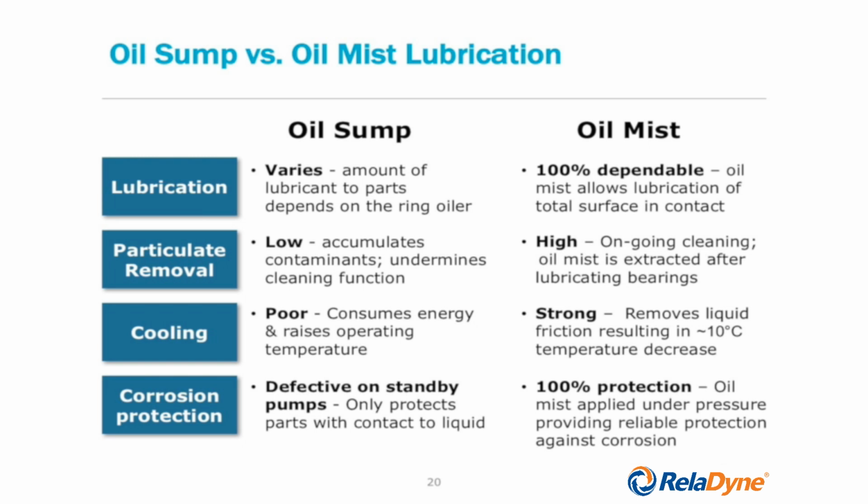We look at particulate removal. Well, if you have an oil sump with liquid oil, then any kind of contaminants will actually drop to the bottom of that sump, but they're not being removed from that sump. And in some cases, in an agitated sump, if there is turbulent flow of lube oil, they may even remain in suspension. And these particulates that have contaminated the oil will actually get into the bearing and cause early distress.